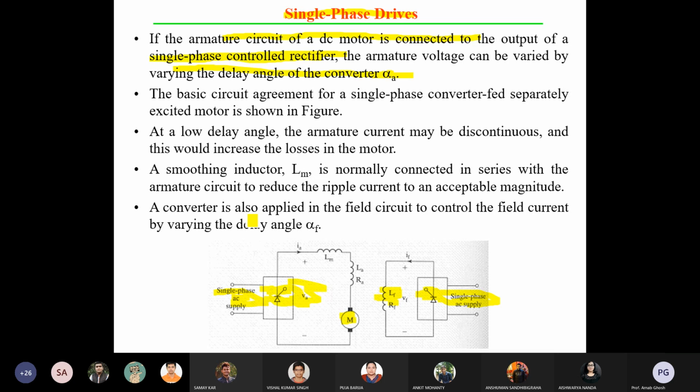That is why you are using a pulse train, but the duration of the pulse train is not long. So why a pulse train? Suppose the first pulse misses triggering the SCR, then the second pulse can trigger it. That is why you are using a pulse train. But why not the entire cycle? The entire cycle is not required.